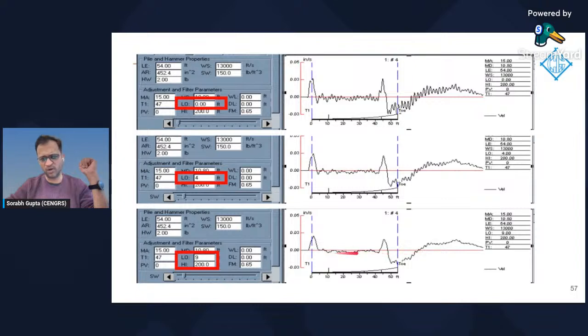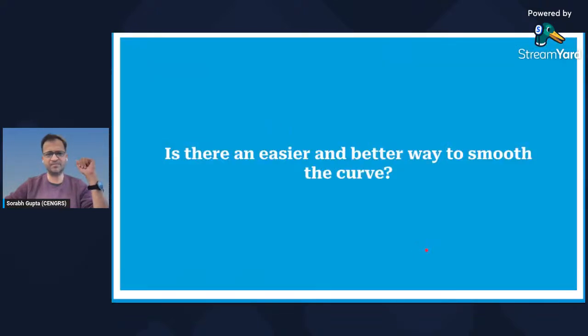Now, I want to point out in this case, either your wave speed is assumed incorrectly or the pile length is actually short. It seems to be around 42 feet, as opposed to what I think they were expecting, a pile length of around 54 feet. So that is what's going on here. But what we must focus on is using the low pass filter. You can go from here, and naturally, when you have data looking like this, interpretation is a lot easier and you make fewer mistakes.